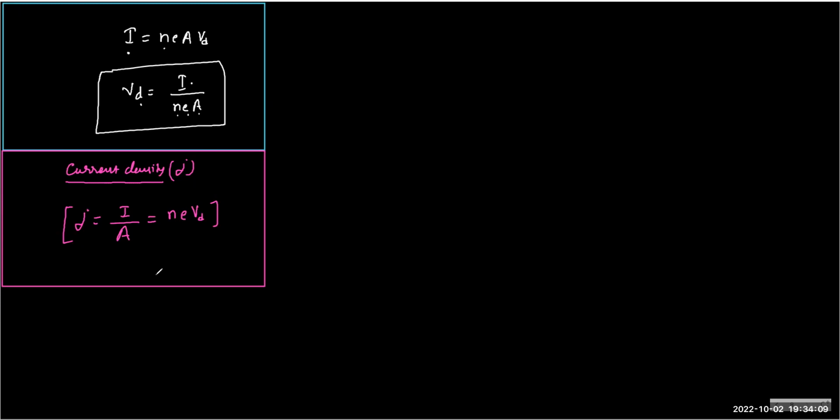Yes or no? If I take the same cross section and cut it into small patches like polka dots, then will every tiny polka dot have the same current or different current if it is non-uniform? Different. Common sense. So current density is a point property, current is a surface property. Understood?